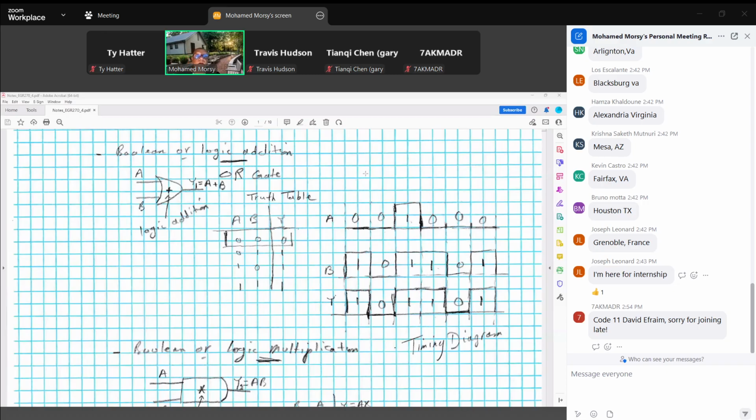Okay. So yeah, there is no other. This means the output has zeros at only these two intervals. Then without looking for the others, the rest are ones. So we have 0 here and 0 here. Before is 1, and after are ones until we reach here, and then 1. So we figure out the time duration where the output is 0 based on the two inputs simultaneously being 0. Then automatically by default, for the rest we just put ones. Everyone sees this?